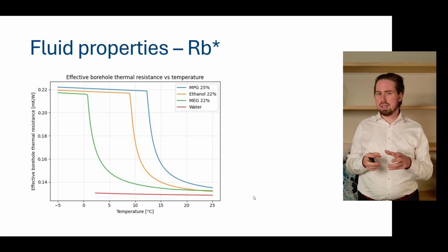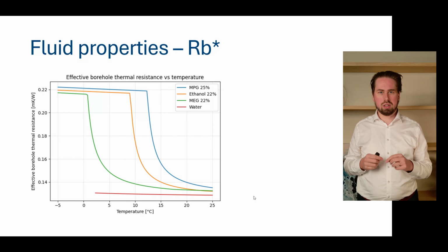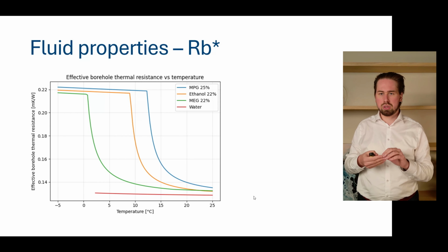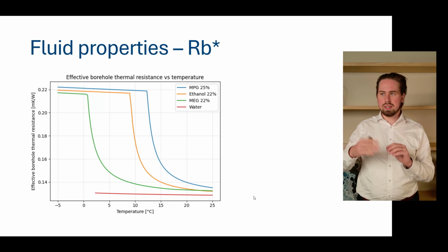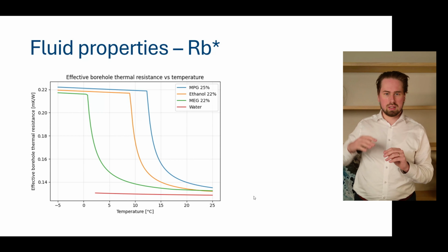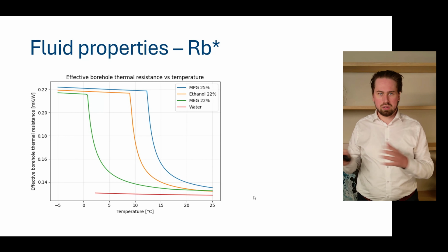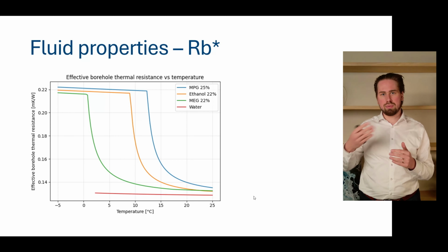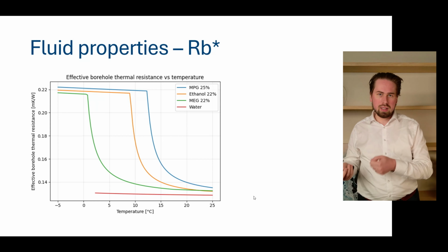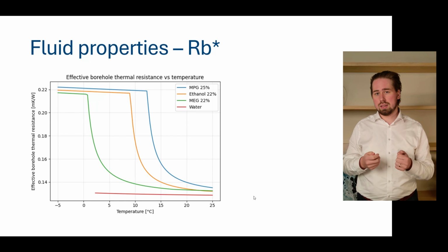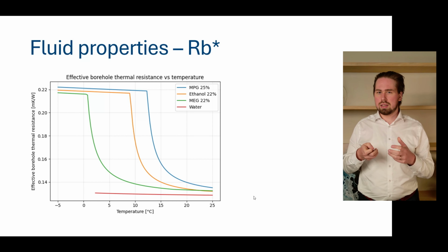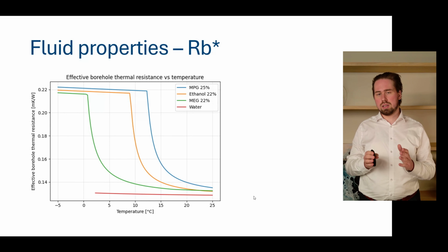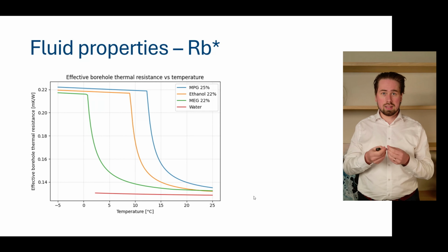But the interesting thing is that in your borefield simulation, your temperatures typically vary quite a lot. You can easily have temperatures in winter of around 0 degrees and in summer around 15 degrees. So, of course, when you're switching from heating to cooling and the temperatures in your borefield fluctuate, you will also move in and out of turbulence quite often. And this is something that has not been taken into account over the last decades. And that's why in GHG tool we now added this explicitly.